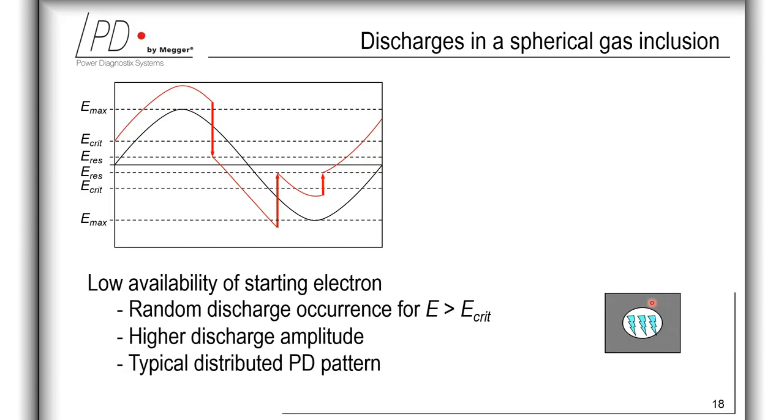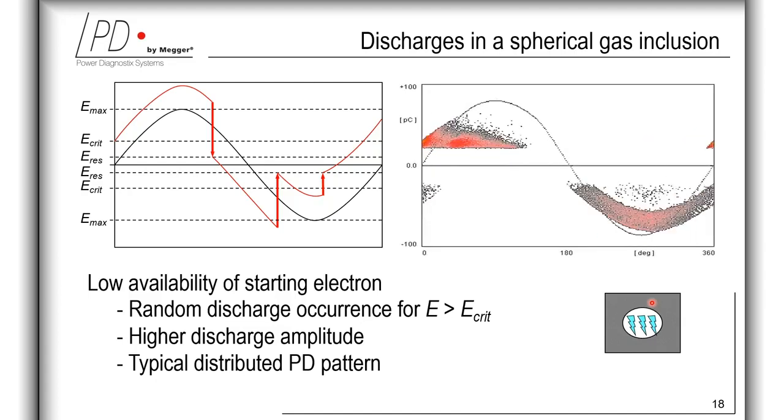As the internal surface conductivity of such fresh voids in polymers is in the range of 10 to the power minus 15 Siemens, these surface charges can survive several tens of milliseconds, and they always would remain available for the so-called detrapping mechanism.